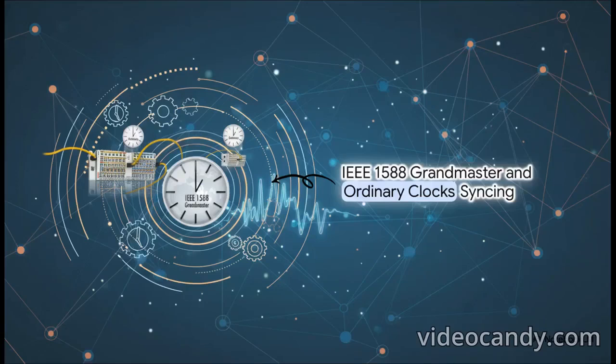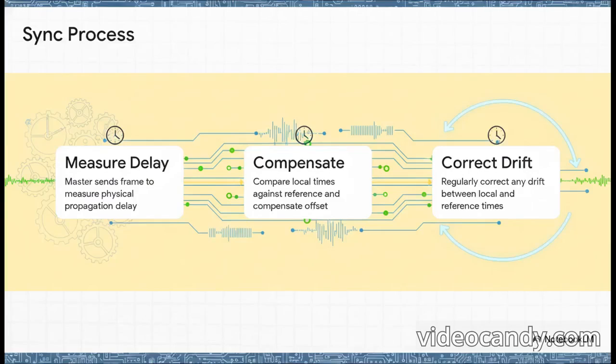Section 3, mastering distributed clocks and nanosecond alignment. Now, fast frames alone just aren't enough, right? We need an impeccable timing foundation to trigger simultaneous movements across a massive factory floor. Instead of trying to force perfectly synchronous communication, which totally falls apart the moment there's a tiny network delay, EtherCAT uses a distributed clock system. A reference clock, which is typically the first device right after the master, orchestrates the synchronization across all the subordinate ordinary clocks in the network.